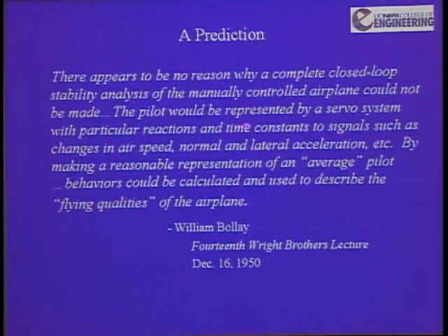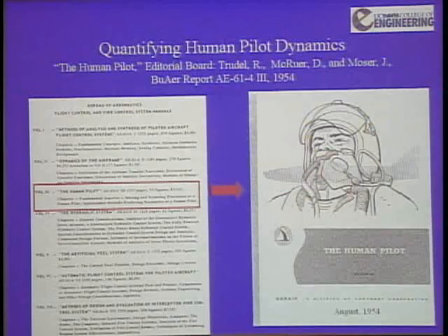The pilot would be represented by a servo system with particular reaction and time constants to signals such as changes in airspeed, normal and lateral acceleration. By making a reasonable representation of an average pilot, behaviors could be calculated and used to describe the flying qualities of the airplane. That was the first time this was said, and that really kind of sets the tone for the talk, because that is indeed what occurred as time rolled on.